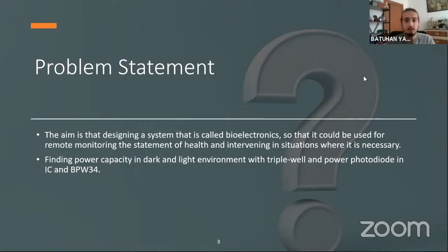The purpose of this conference project is to compare the performance of integrated CMOS photodiodes with alternatives available in visible light communication systems. We use 3 different photodiodes and compare them, and then test their performance through multiple tests. We are trying to determine the most effective components. In this work, we maintain the same resistance in dark and light environments on BPW34 and CMOS photodiode integrated circuits, and obtain different current and voltage values by changing the distance.